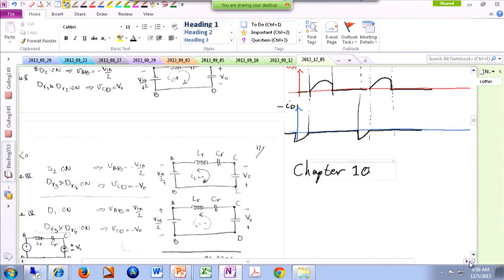All right, so the switch that we are talking about is either a MOSFET, like this one is an N-channel MOSFET, or an IGBT, like this one is an NPN IGBT. Technically, when we say turn the switch on or off, we mean that from gate to source of both of these devices, you can argue that there is a cap, an internal kind of cap.